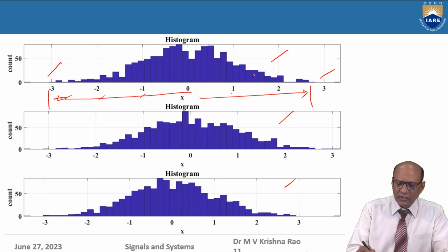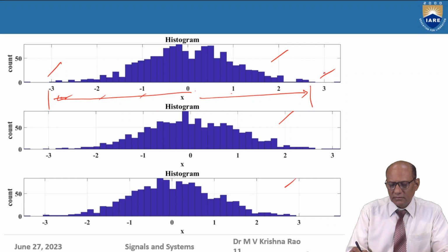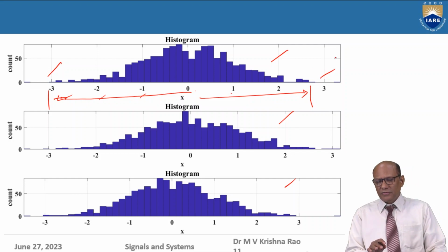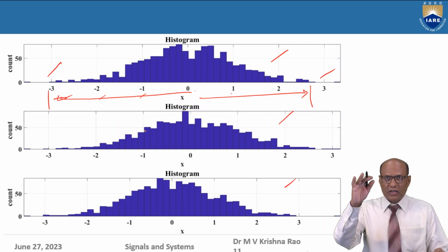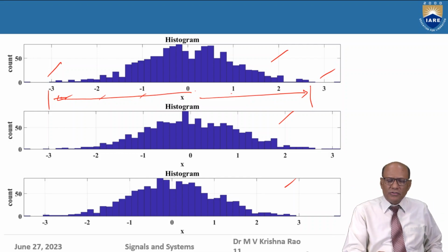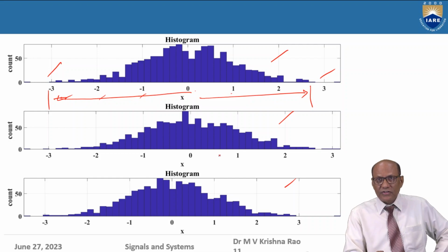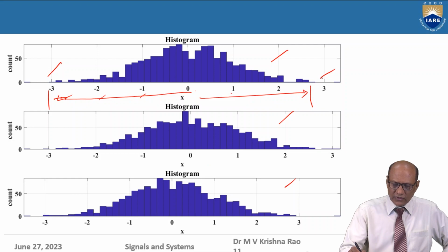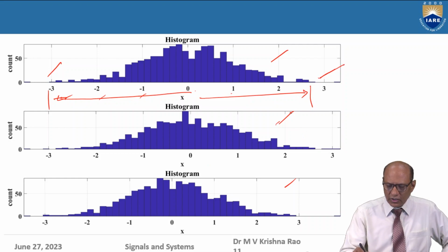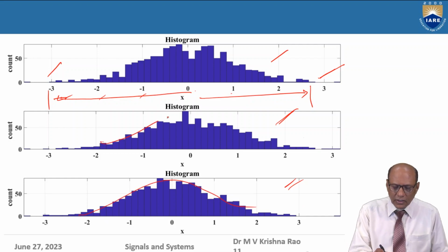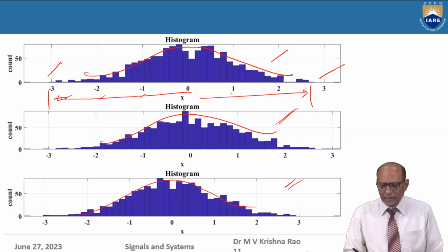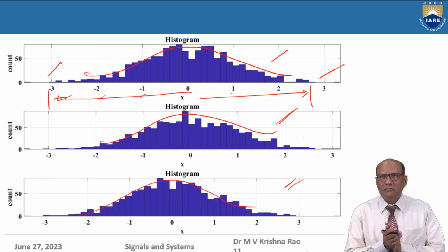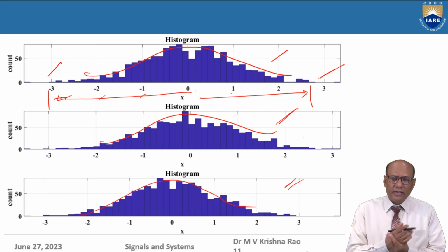Here, for the first time function, the shape appears Gaussian, but there is no smooth curve because the number of samples is small. These are basically estimations, with an insufficient number of samples. The first waveform has this histogram, then the second, then the third. All look similar when I take the global property, as if smoothing; they appear the same, but they are not exactly the same. I will come to the ensemble later.